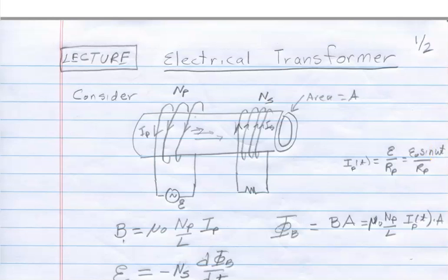Well, you can get I_P. It's simply the EMF produced by the generator here, divided by whatever the total resistance is in all of this. And there's actually a fair amount of resistance because, remember, these electrical generators involve a coil of wire, so they might be a fairly lengthy thing. So in any event, you get a sinusoidally varying current that oscillates back and forth.